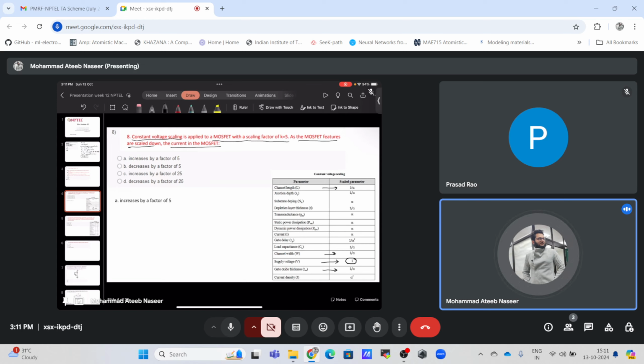As a result, because we know W over L, they are reducing by the same factor, and C ox is epsilon ox by T ox. So to a first order, if T ox is reduced by alpha, it means that the oxide capacitance is increased by alpha. Since this C ox directly comes into the expression of the current, for a constant voltage method we will have a current which will be directly scaled by alpha. The current will scale by alpha, but this will have a serious problem.